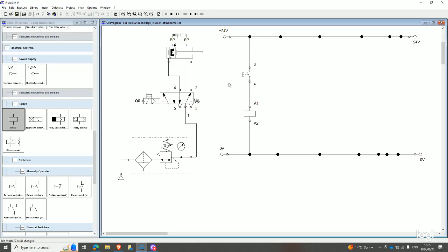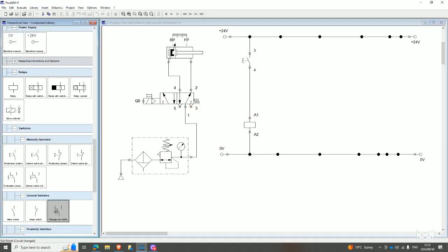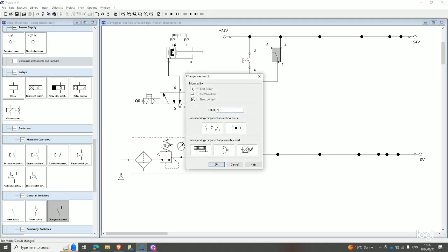And then for you to latch, since this is the push button and your relay is the output, you need to latch the signal of the output. So you ensure that the cylinder is able to remain in the advanced end position, even if this 5-way is spring loaded. So you'll latch like this, so that it's able to maintain that signal. And then you label this R1.